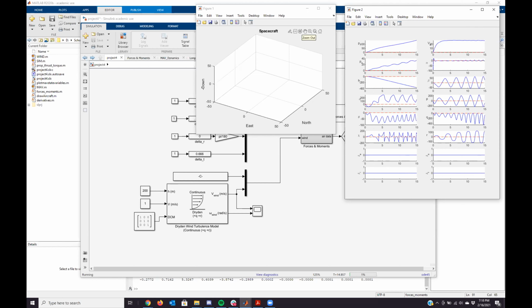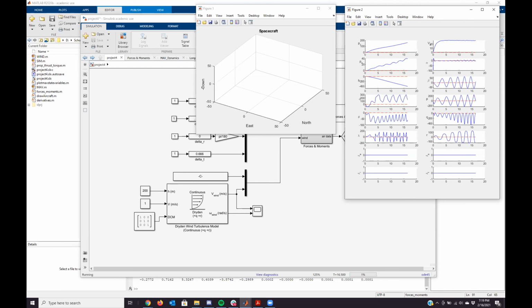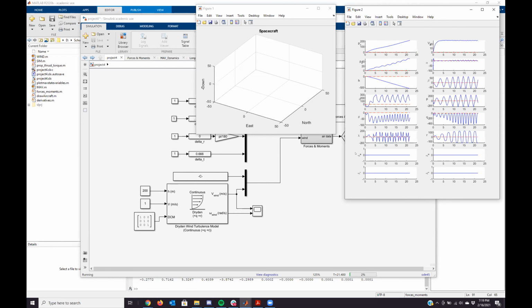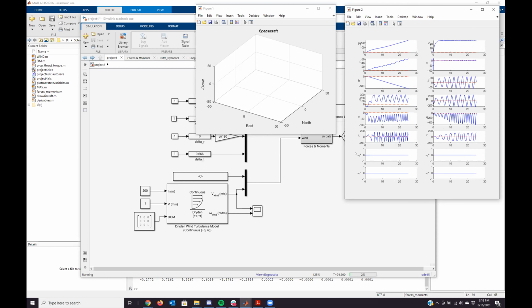I would refer you to this PDF file and ask you to read through it. The aircraft that we are using is inherently stable. What might have happened is a plus or minus sign error in the coefficients. The second thing, and this is important, and I don't want to give out the answer because you have to study it: control of the Zagi is slightly different from the control of the Aerosonde.